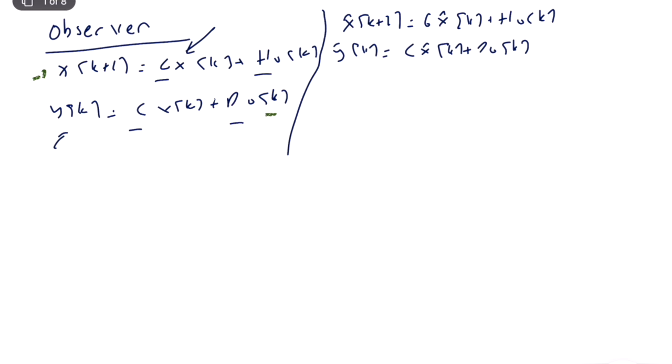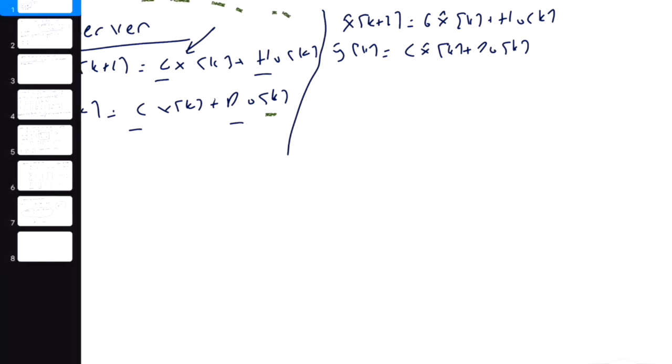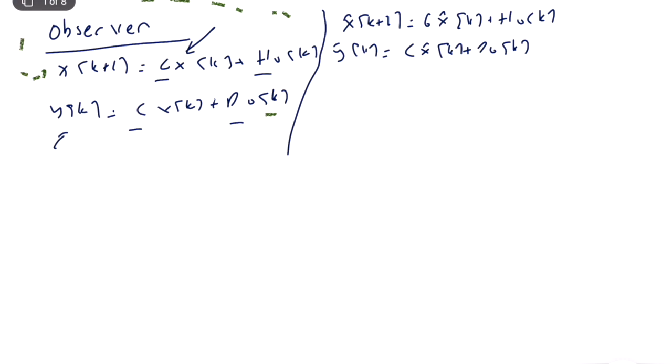That's it. Okay. So I can run the simulation in parallel to the actual system, but the problem is if I don't have any connection, if I have an error in x, it will persist throughout the simulation, right? So I need to match these two systems, possibly connect them such that this x hat somehow converges to the actual x of the system over time and possibly as fast as possible. This is a requirement from an observer.